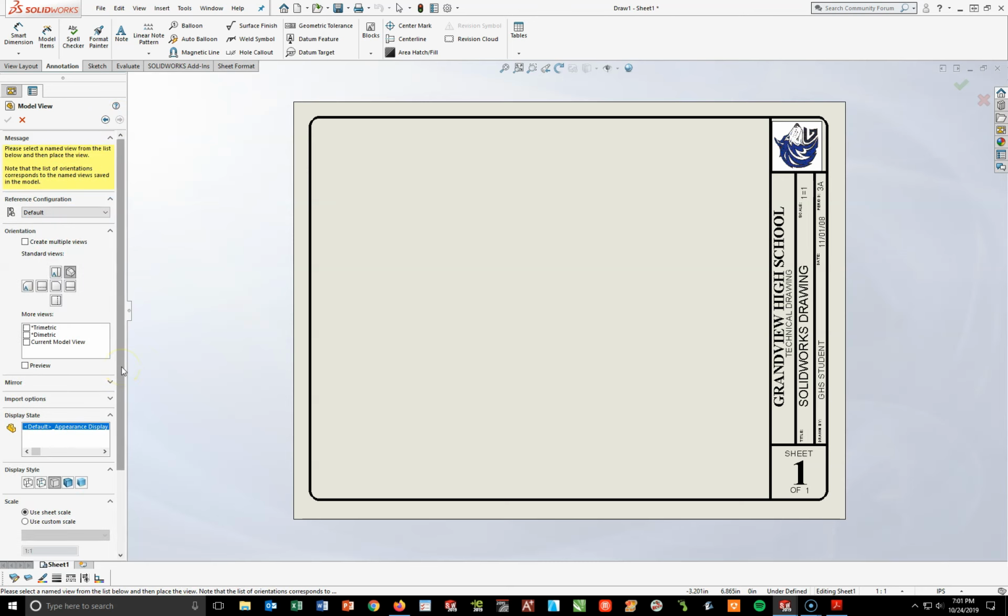Now, this is one of the most important steps, and this is what we'll be doing for pretty much the remainder of the year. I'll do a few manipulations down the road towards the end of the school year, but right now, all of the drawings we're going to do are going to be set up pretty much the same way. It's a 4-step process. The first step is we've got to identify what view we want to bring in. So we're going to start, like we did with our hand drawings, with the front view. That's right here in the center. So here's that unfolded box. There's my front, there's the left, there's the back. This is the right, here's the top, here's the bottom. We are going to start with our front view.